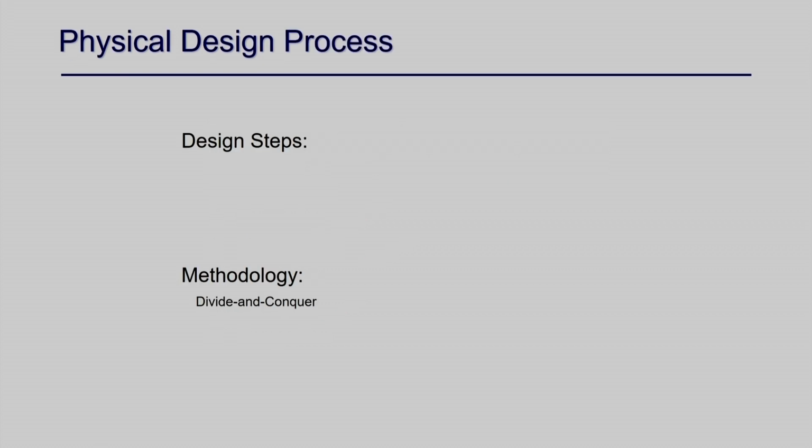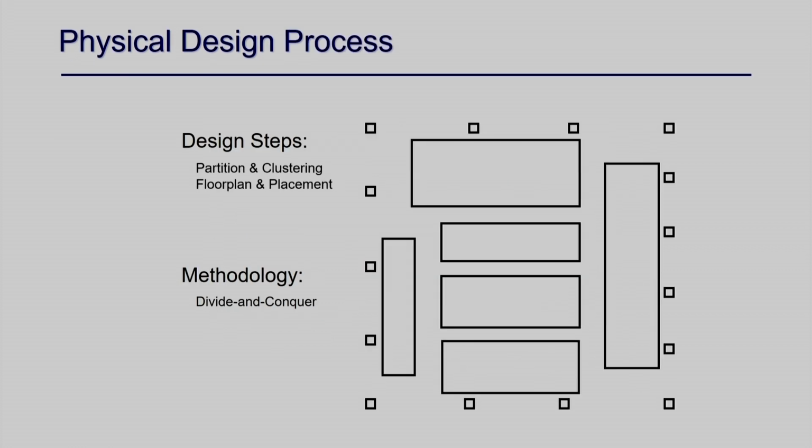When you have a big design, the first thing we have to do, suppose your design has say 1 million gates, and we want to place them, but placing all this 1 million at a time is kind of an impossible job, right? What is the basic approach we usually follow in life? Whenever you have a big task, we partition it into subtasks, solve the subtasks, and then combine the results. The same approach is happening here.